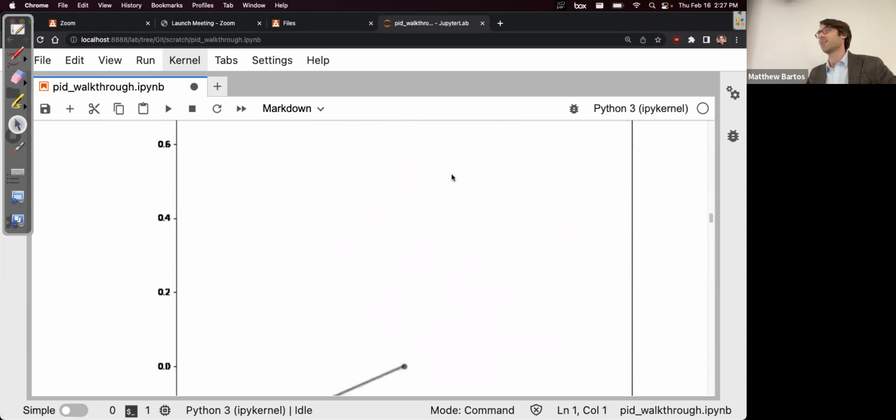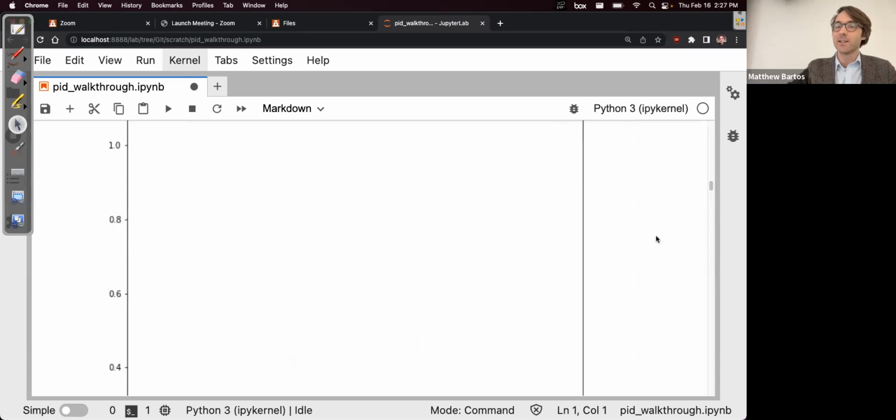So, first of all, is this how the actual system is going to behave? No. Why is it doing this? Right, so 2 reasons. One, it doesn't have the boundary conditions corresponding to the ground. What's the second reason? What did we do to our original equations of motion? Yeah, we linearized it. Linear functions can explode to infinity, whereas nonlinear functions often saturate.